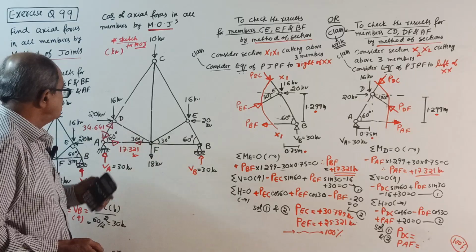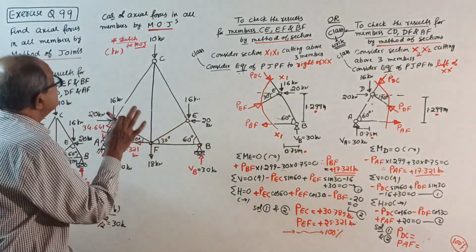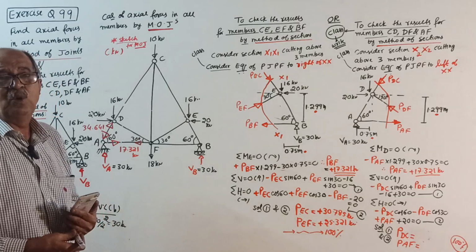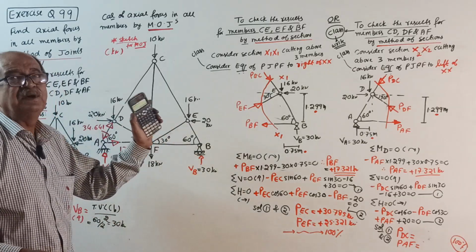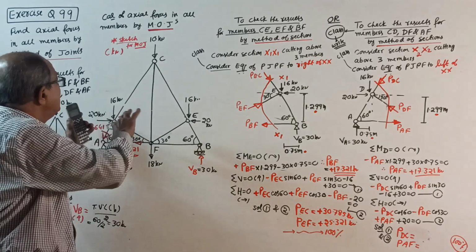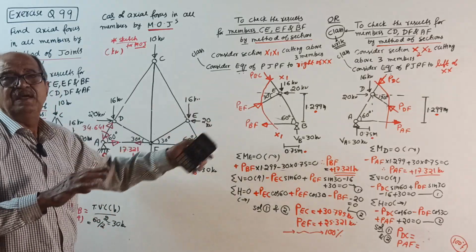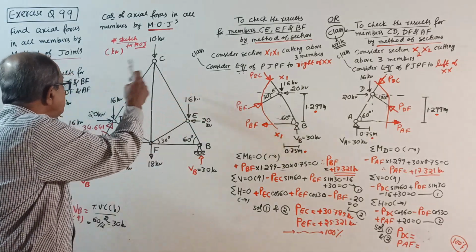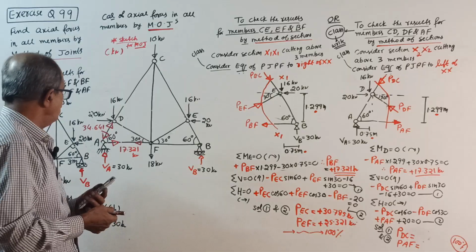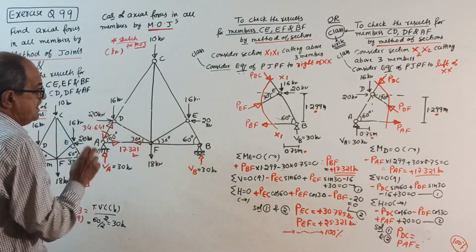Now, if I go to the joint, joint B is not required. See, symmetry is there. So make one more note. Solve only half the frame. You solve from the left side. When you cover 50% of the frame, leave it, enter the answer that side by looking at this side. This I told you. Okay, now I will go to joint D.